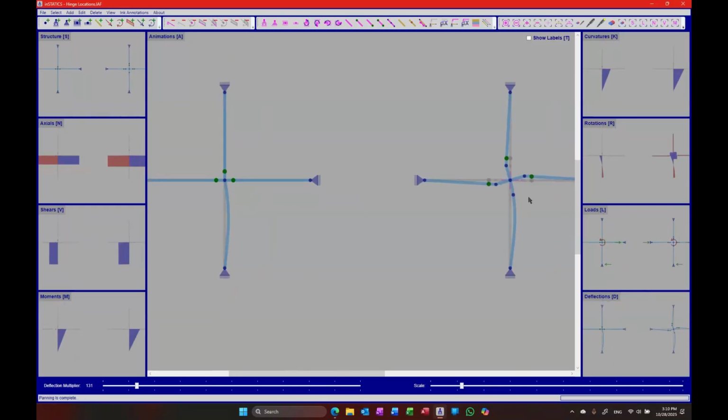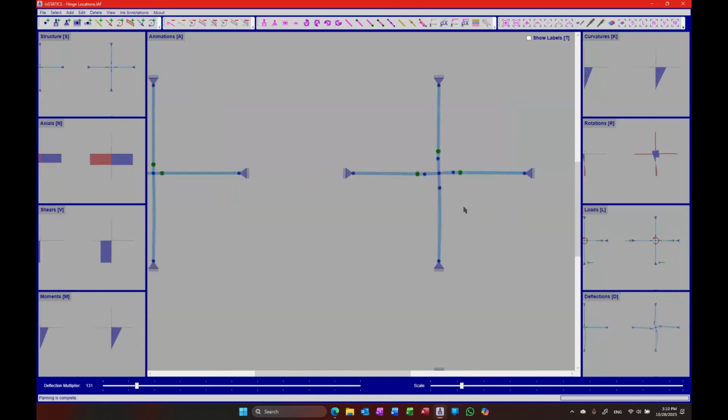So what I did is I added these short links to offset the hinges a little farther so you can see how adding 3 hinges actually works. It makes sense, right? These won't get a lot of load or no load because they are pinned and they have a hinge, so you're not going to get any moments on them. But there's at least one element that can take that moment, right?